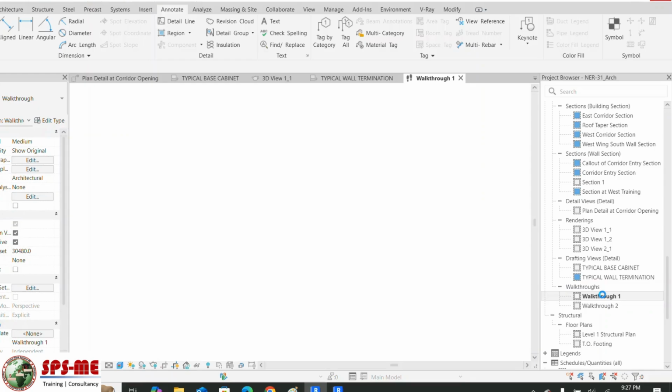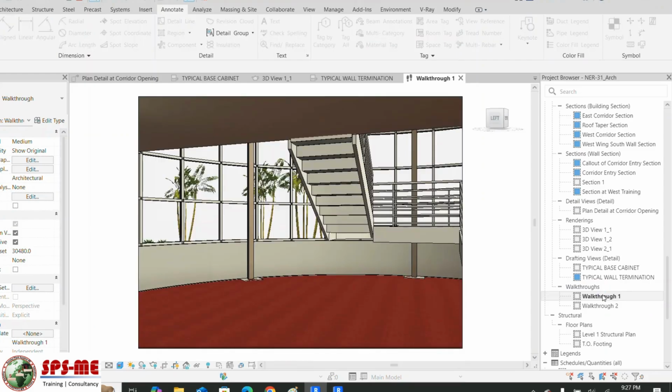That's also possible. Then we have here the schedules. We said that in BIM we give the information while creating. For example, you place an air terminal, so you have to give the size of the terminal and the height of the terminal, I mean, from the floor level, what height it is going to be placed. All these details we need to provide. Same with a door: what is the height of the door, what is the width of the door, the material information, hardware information, everything we can provide.